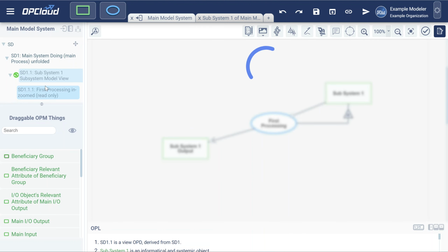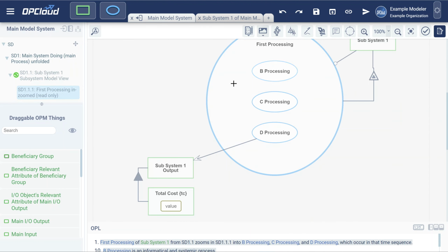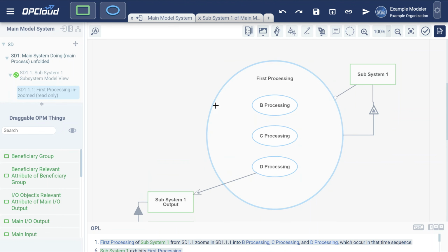And now if I go to the other parts, you will be able to see that it fetched whatever I've updated and saved. You need to save the submodel in order for the main model to take into consideration the synchronized part. Another thing you need to know is that the checking if the submodel is synchronized or not on the main model is up to 30 seconds.